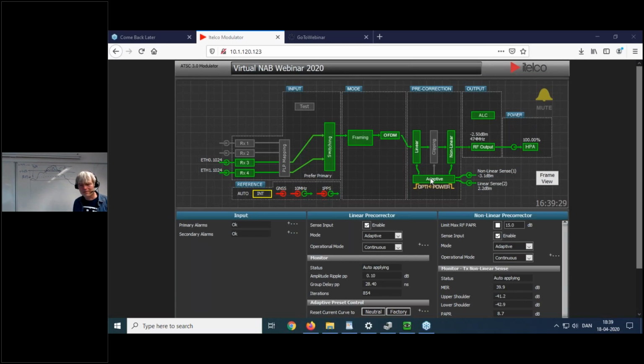Of course, with better precorrection, it manifests itself either as improved MER, which could mean a better lock or a larger coverage area, or more efficiency. You can turn it off. You use it the way you like it, yes. And Morten, this is appropriate to both television and radio, yes? All waveforms which are multi-carrier, Perry, you are right. So for the single carrier, we don't need it, because that's constant magnitude and only phase modulated.